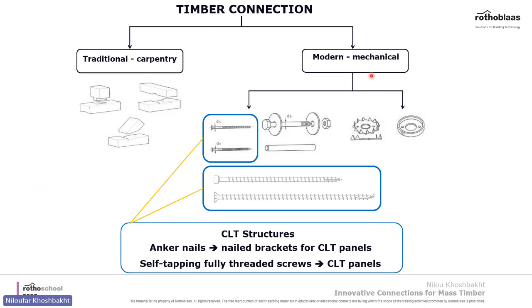In terms of mechanical connections, nails, bolts, and plates and screws, they all have been around. But the thing is, these connections are mainly designed to deform, to resist lateral loads without making any splitting or fracturing in wood. So there is less fabrication on the wood side and significant savings with metal connectors and screws.